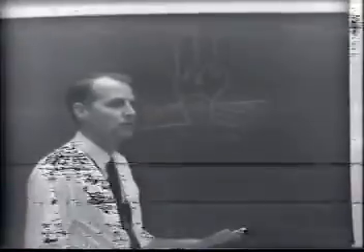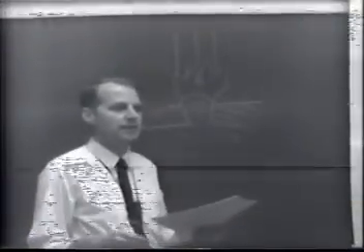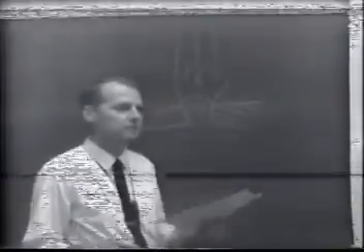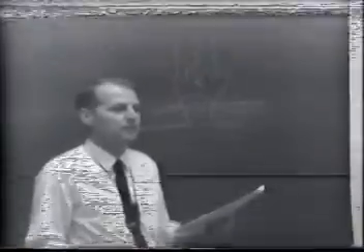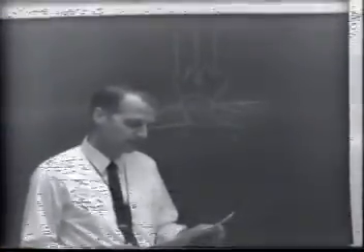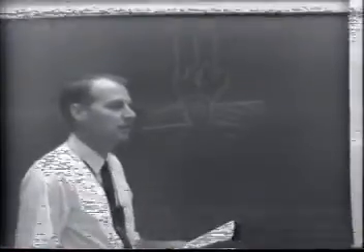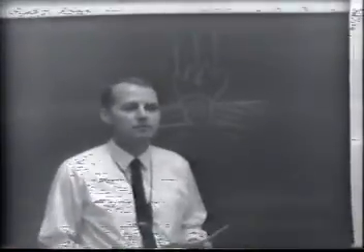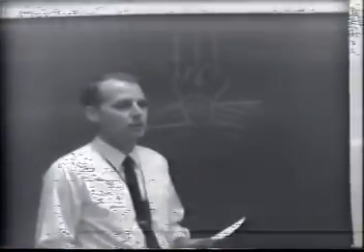Second thing we want to do is to cool it. In cooling the arc, we would tend to deionize the gases. That means allow or force or tend to bring the conditions about that will combine the electrons and the protons and get back into the original materials that we had to begin with. And we can do this, for one thing, by having the arc in a cool medium, which might be a tank of oil.